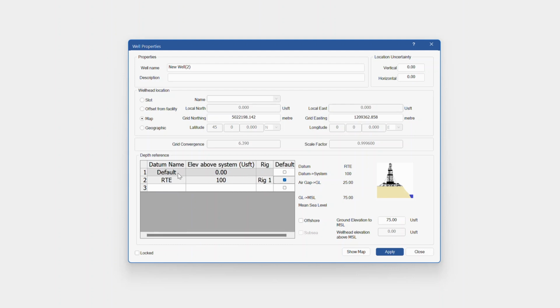Now you can have as many depth references within here as you wish. If I want to do some initial planning to ground level, put my ground level value in here. And the thing is, for each line within here, the ground level is separate, so it's not used across the board. Now that I've entered a line 3, I have to come down here and fill in my ground level again. So does this make sense? I've got an air gap of 0, so yes, that makes sense. The ground level entered in here, same value in here, and we can then utilize this in the planning.